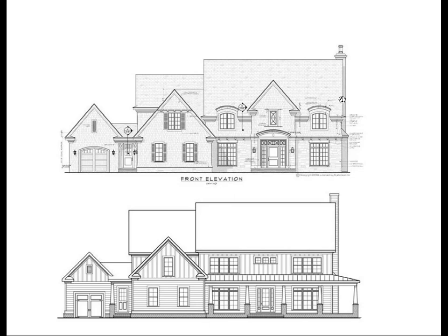Without those, if you were to draw everything on the zero layer, I wouldn't know, as the architect or the contractor or whoever's reading these, what plane each of these things are on without looking at a floor plan. By just looking at this, I should be able to tell where a certain thing is located, in generalities. I should be able to tell that this plane is closer than this plane over here by having the correct line weights. So that's it for our little slides, just a couple of examples of elevations that I wanted to share.